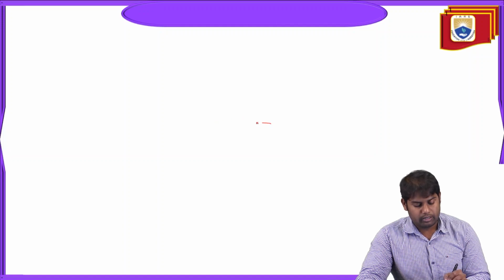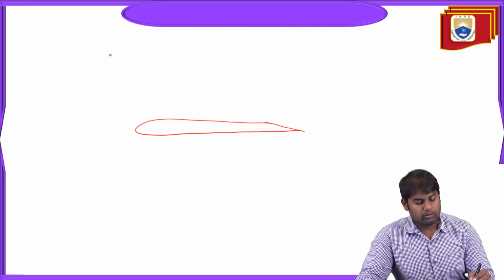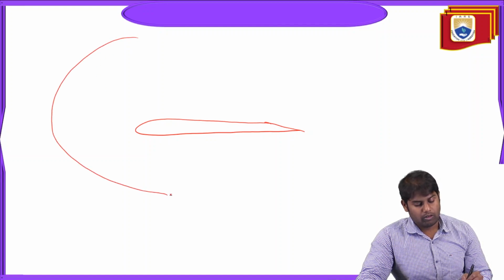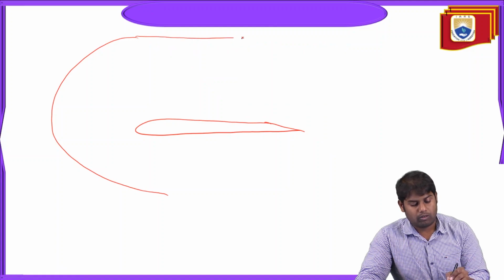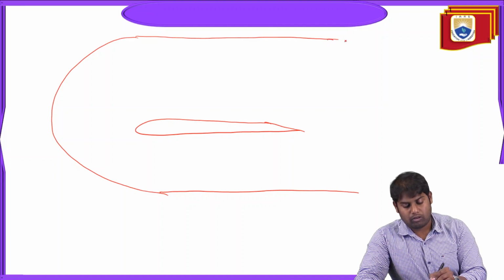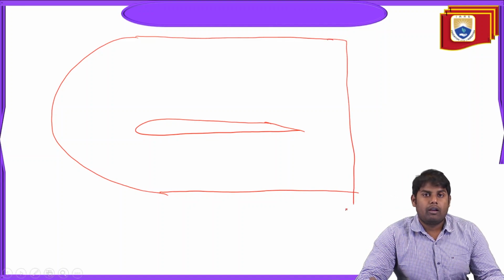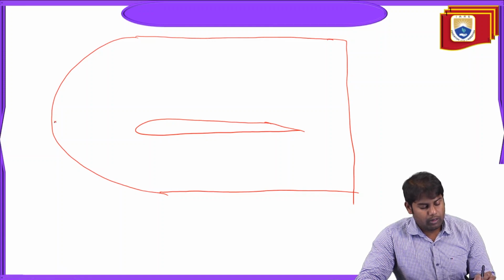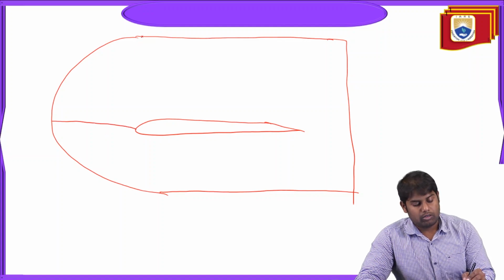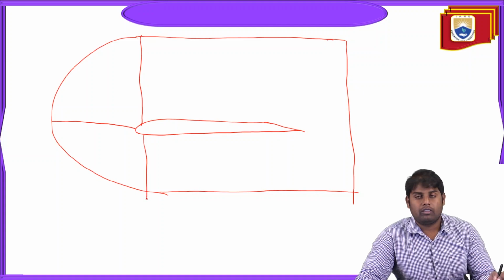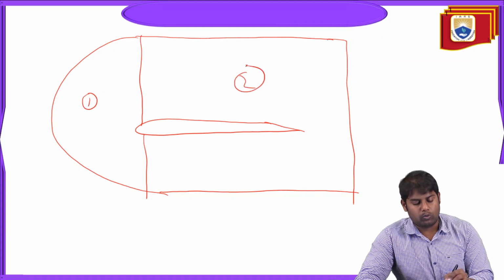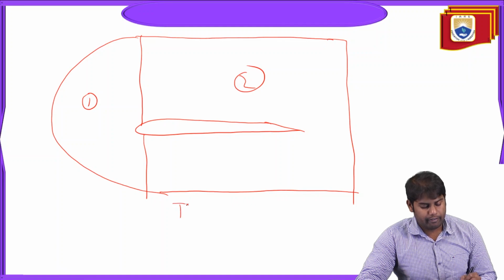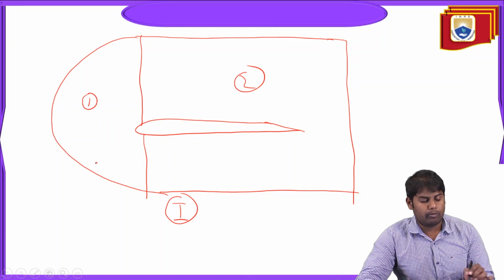Again we'll see, this is the airfoil we have. This is the C-type mesh we have. Initially this is the mesh entity that we have. Now what happened? We initially drew a line like this. We already have this line. Initially when we don't have this, this is a complete C portion. This is domain 1 and this is domain 2. Overall this is called the domain entity 1, but this domain entity is divided into 2 subdomains, 1 and 2.